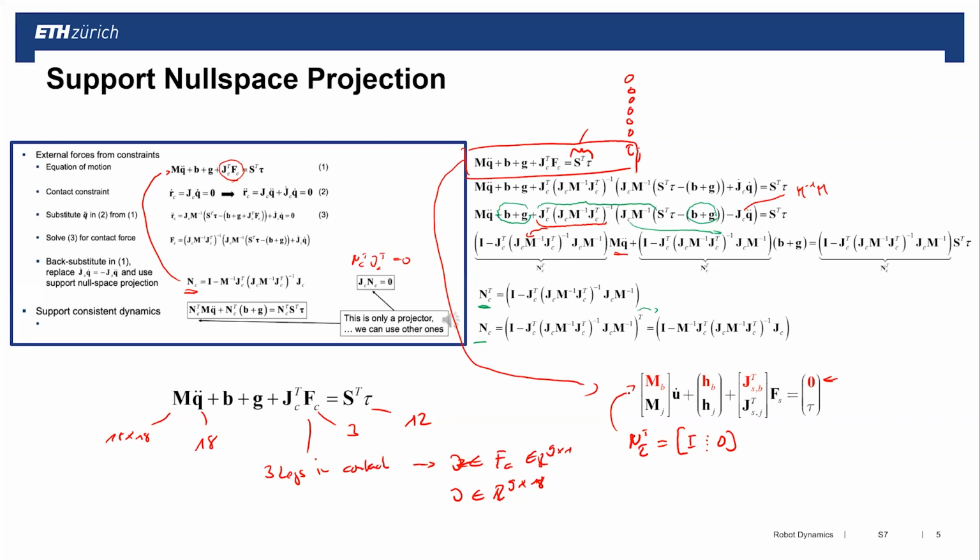So we make it now linearly independent of torque. Essentially, the null space projector is now the null space projector related to the actuators. And similarly to what we're doing here for the actuators, you can also understand what is happening for the support part. So we're using dimensionality and just looking at that part which is relevant for these two parameters.